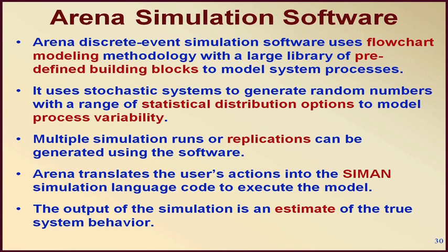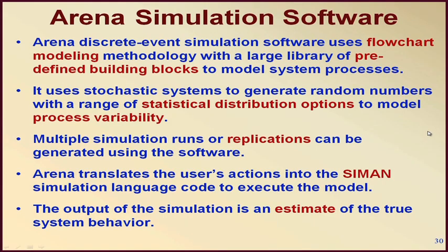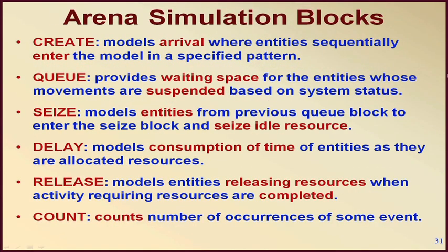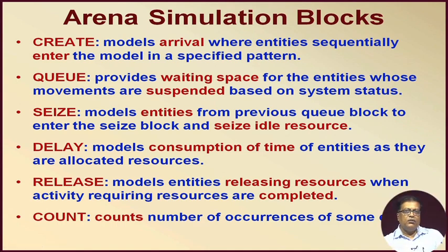Essentially the ARENA software really works on a large number of predefined building blocks. So, what are those predefined building blocks? Let us see them. Here are some of these building blocks. The very first building block is called a create. The create actually models the arrivals where entities sequentially enter the model in a specified pattern.